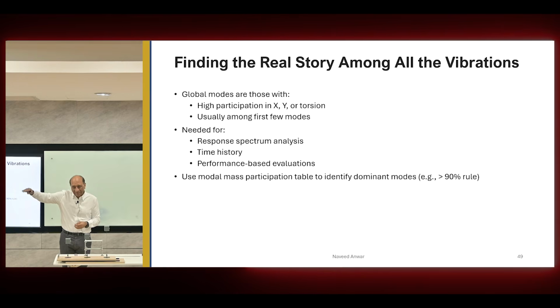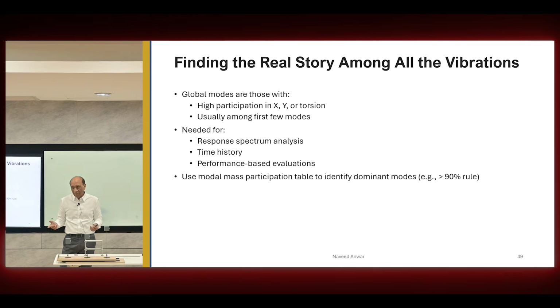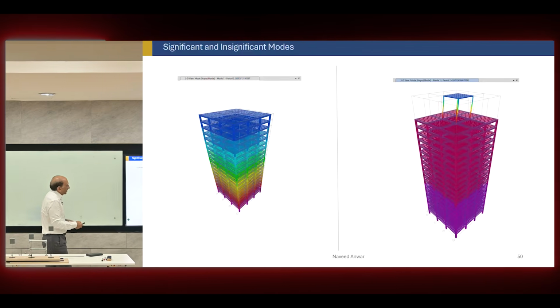For example, maybe one cantilever is moving. Maybe a building has a very large cantilever, so that might start moving before the building moves for an earthquake. So that's a problem for the cantilever, but it's not going to have any modal participation for the earthquake. But that will still be something that you should worry about. So this is one example.